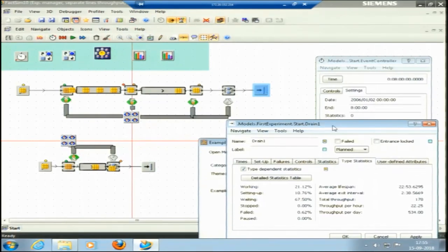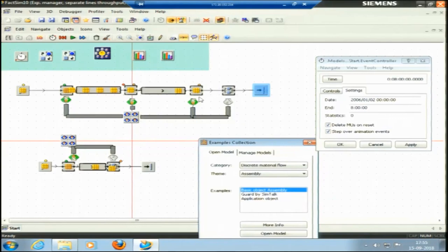This is based upon the input that we have given to the specific processes, which I will discuss. It is the setup time, processing time, then the availability: is it available for the complete time or for 95% or 90% of the time. Then we have the distribution. For a manual process where we do not have much data, only 2-3 data points, we can pick maybe a triangular distribution. If it is an automated process, I can pick a normal distribution with very little variation. Based upon the inputs we give, the software will simulate and give us a throughput.